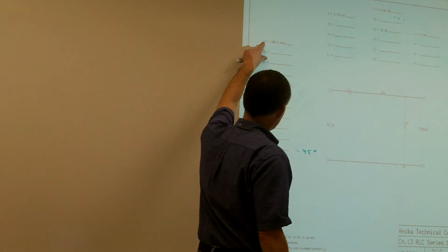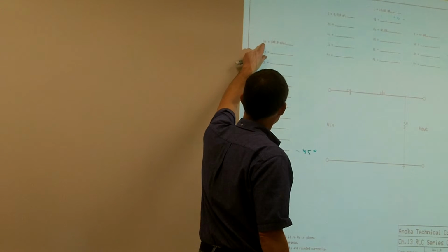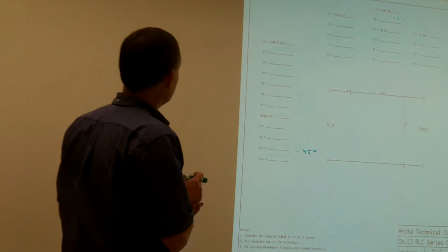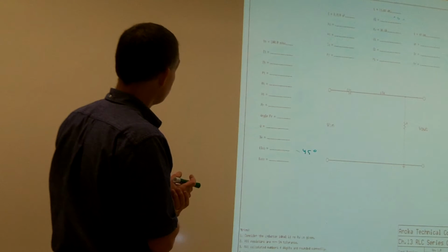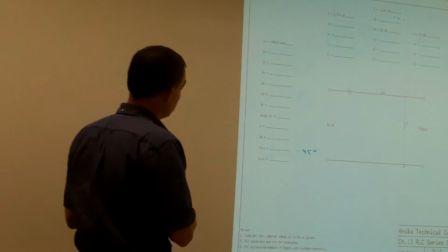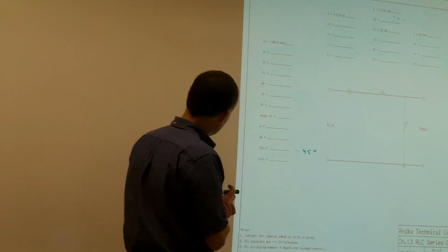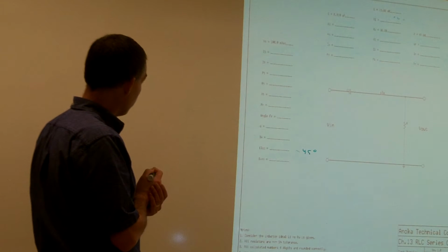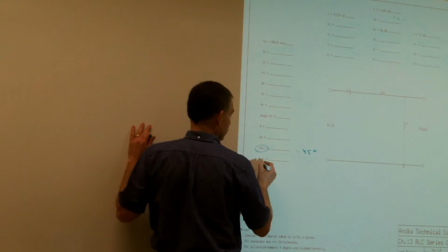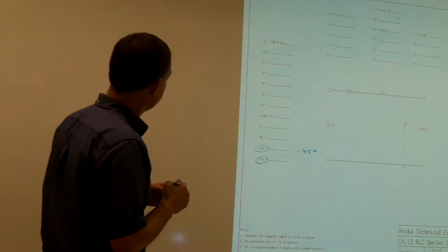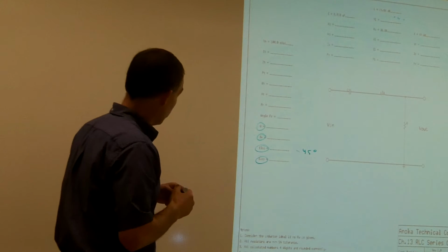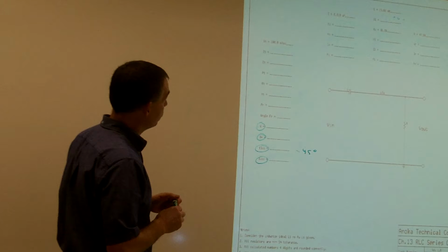if I use my voltage source and my angle of negative 45, I know that I can find out what my voltage across my capacitor would be. And then I would know also what the voltage across my resistor would be at that point. I'm trying to think in my head here. I could actually calculate out my resonant or my lower frequency cutoff, because that's what you really want to know: what is this and this. But I don't know, since we already know how to do it by looking at the quality of our circuit and calculating all our bandwidth from that, that'd probably be the easiest way of doing it.